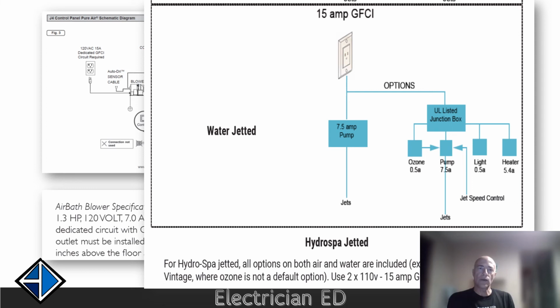But you could put a single receptacle near the equipment and protect it from a GFCI breaker, or even with a blank face GFCI nearby to serve double duty as both the GFCI protection and an emergency disconnect. A blank face GFCI is a GFCI receptacle, except that it doesn't have the receptacle ports. It's just blank face, but it's got the reset and test buttons.